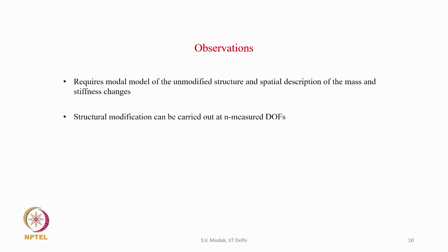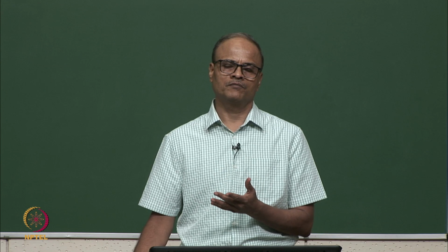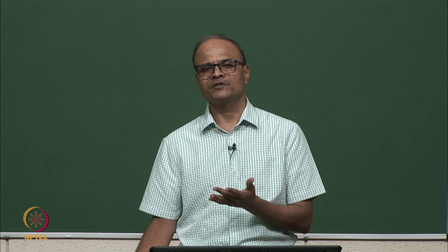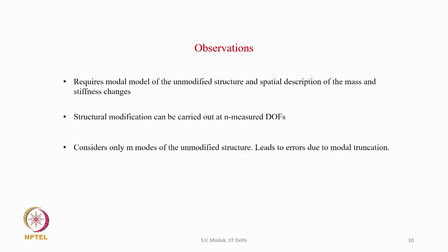But one constraint is that the structural modification can be carried out only at the n measured DOFs, because the model is based on measurements at n DOFs, and therefore, the modifications that are introduced, the lumped mass modifications, stiffness modifications or other modifications, can be introduced at and between the points which belong to these n DOFs.